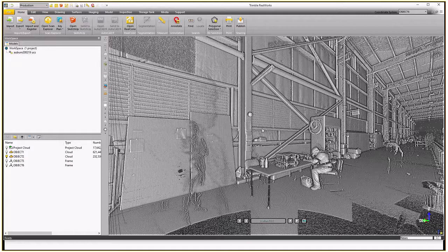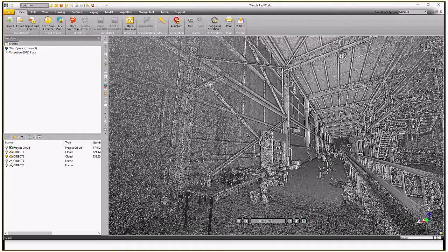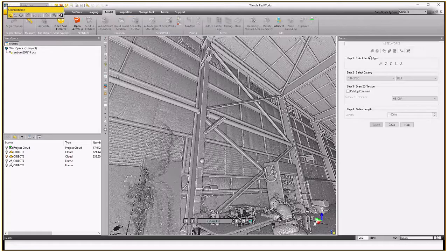So this is a rail yard thing where they bring the carriages in for repairs and stuff out at Auburn. So if we jump into the modelling tab here, I'll select cloud. We've got these Steelworks options. So we're going to model some Steelworks. Firstly, I need to just segment out part of a beam so we can fit a beam cross section to it, and then from there on we can duplicate that to all the other beams. So I'll just select that section of that beam there.